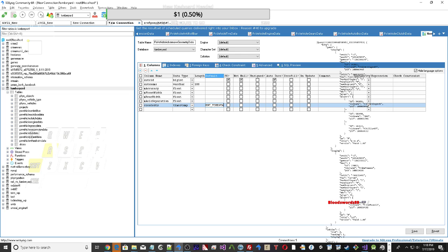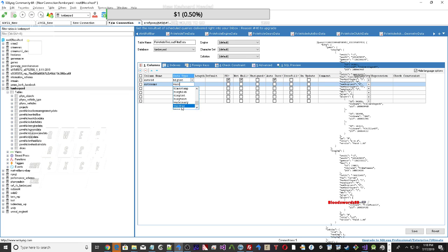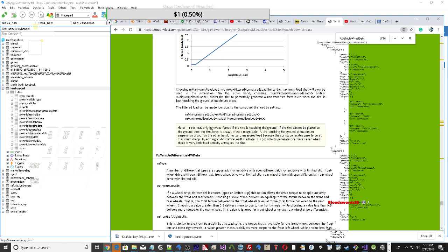A PxSerializationRegistry instance can be created with PxSerialization::createSerializationRegistry. The basis vectors of the vehicle simulation must also be configured so that longitudinal and lateral tire slips may be unambiguously computed. void PxVehicleSetBasisVectors(const PxVec3& up, const PxVec3& forward).